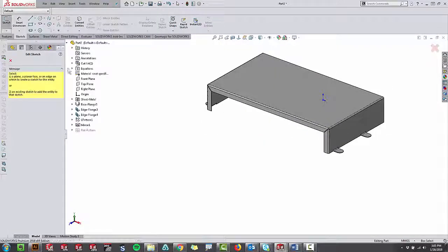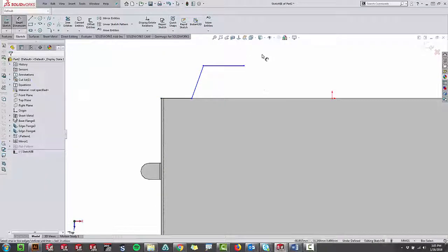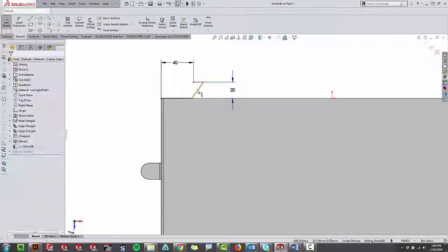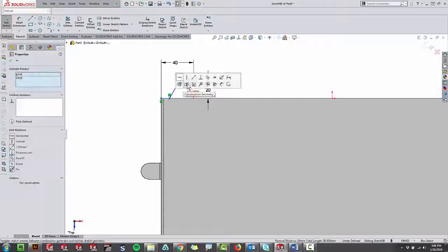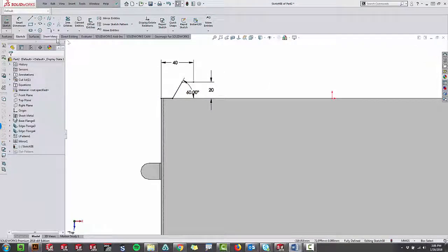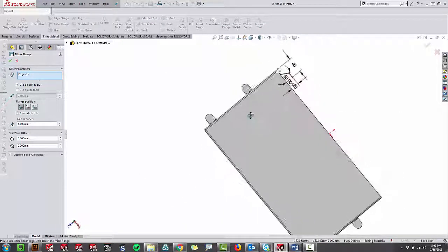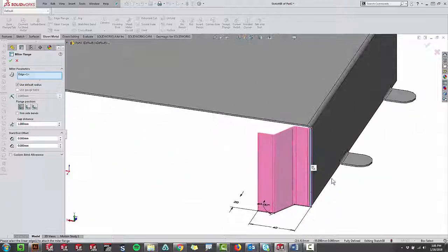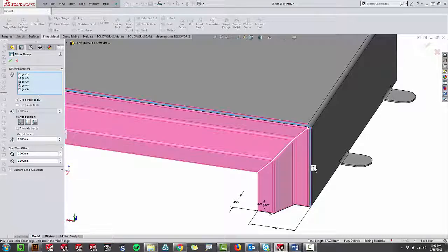The next flange we will create will bend 3 different times. And in order to stay as efficient as we can be, we're going to create them in one single feature. Just like before, we're going to add some dimensions and relations in order to fully define our geometry. Now, allow me to show you which are the edges that I want to make part of this particular feature. I want to propagate this flange along the tangency of this highlighted edge. So with a click of a button, I can select all of them.